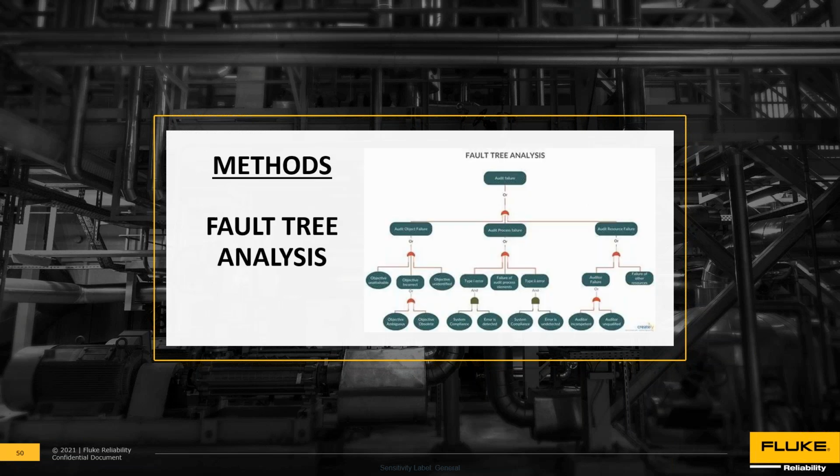So here's a fault tree analysis. This is another tool, and this tool is used more as a proactive approach, more for safety engineering and reliability engineering. You look at, okay, what are the undesired states? Like maybe "stop working" is a little bit too generic, but maybe the fuel valve, we're not getting fuel to the engine or something like that. And then you break that down. What are all the possible symptoms and causes of a problem with not having fuel? Honestly, this isn't one that I've used, but I just want to share that. It is an option, and there could be some times that it might be useful for you.